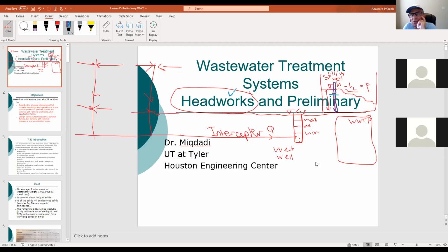This is needed. What is needed also is a measurement. You need to measure the flow. Always measure the flow. Mainly we use a Parshall flume. Similarly with these pumps, because wastewater has objects in it, big ones, small ones, medium, different kinds of impurities and trash, we use open devices here, not closed ones.